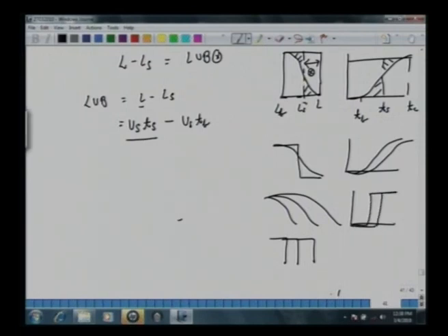So we define this quantity LS, and we move this region from here to here, or we move this region from here to here. Make a note that we can write that this length gets saturated when the front has reached LS. So that is US times TS. And then we have this LS, which would be US times TB, the time at which the first breakthrough takes place. At that time the ideal front would have been right here. So we have US TS minus US TB, the length of unused bed, which is this.